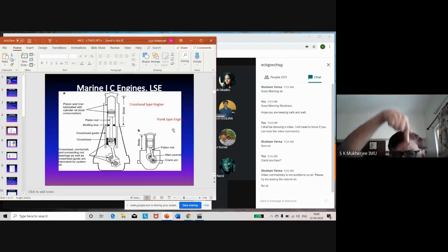The piston gets a vertical force, no doubt, but that force is ultimately translated into an angular force. This angular force is passed through the connecting rod, and it is maximum when the piston reaches its mid-stroke position, because that is when the angle is maximum, and the transverse component of the force is also maximum. And this transverse component is taken up by the wall of the piston against the wall of the liner.